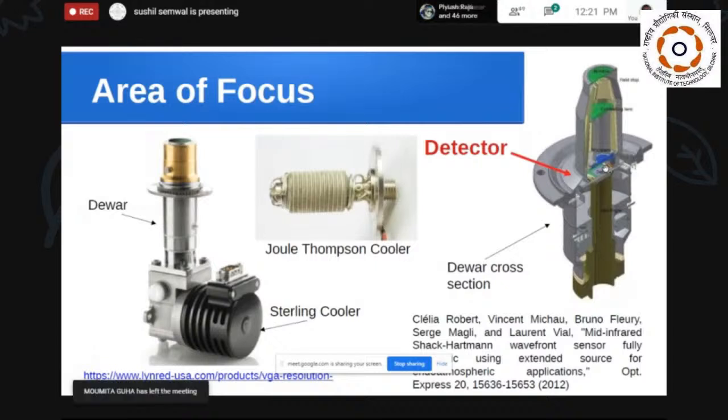One may ask the question why these two layers are used in front of the detector array. This is basically because if this cold shield is not used, then since the outer shield is at the temperature of the atmosphere, whatever scene is being focused from the optics onto the detector will have an extra noisy thermal signal generated from this outer cap, because, being at room temperature, it will itself radiate according to the temperature at which it is.